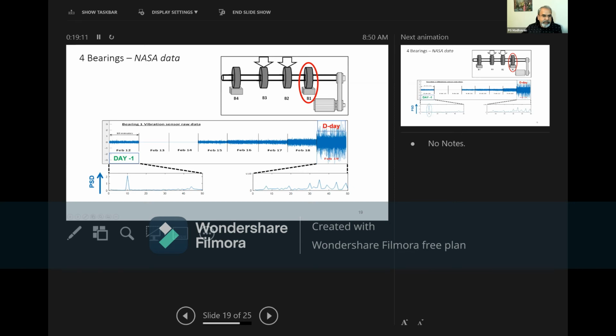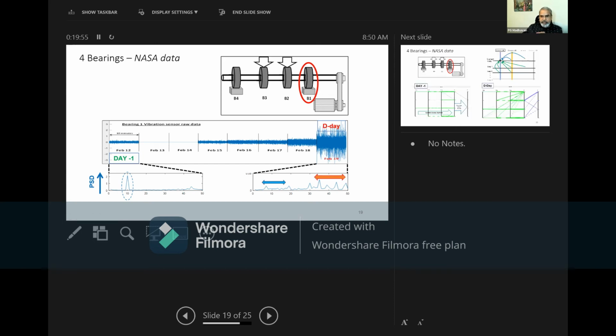If you're a bearing expert, you will say, this one they call the driving frequency or the line frequency. This is just the motor's basic frequency. Initially, when everything is nice and clean and pristine, that's the one that shows up. As things get bad, that driving frequency gets distributed into its harmonics. You won't see that base driving frequency anymore, and the so-called bearing frequencies start showing up. These are high frequency things generated by the many rolling elements rubbing against the inner and outer race. That's why those higher frequencies show up. So that's the spread, and that is what is causing the problem.